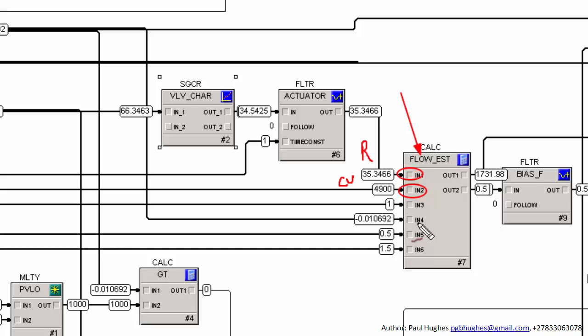The field PV is the measurement from the field, so this is the raw value that we're trying to have a backup reading for. And then we can specify minimum and maximum biases that we're willing to apply. So it's a multiplicative bias. Go into the code.